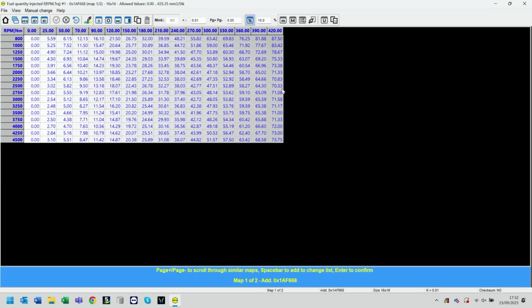Okay, so we've done a lot of investigation here, but it sounds like it's really important because I guess with lots of experience you can just steam in and start changing things. But if this is a fairly new map, that is an insight into how you would approach it before we do any tuning, before we make any changes. That's the work that you would do to understand what your parameters are. Yeah, you need to understand the data inside of the ECU, and it can take a little bit of time. We've gone through it quite quickly there. I am familiar with this software platform. But even if it's a brand new ECU you've never seen before, go through each of the maps and build up that, as I said, the notes I've put down on the page here.